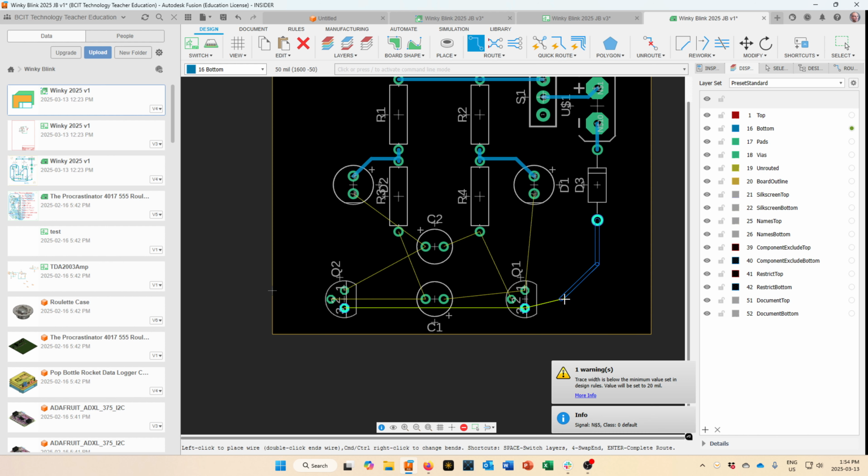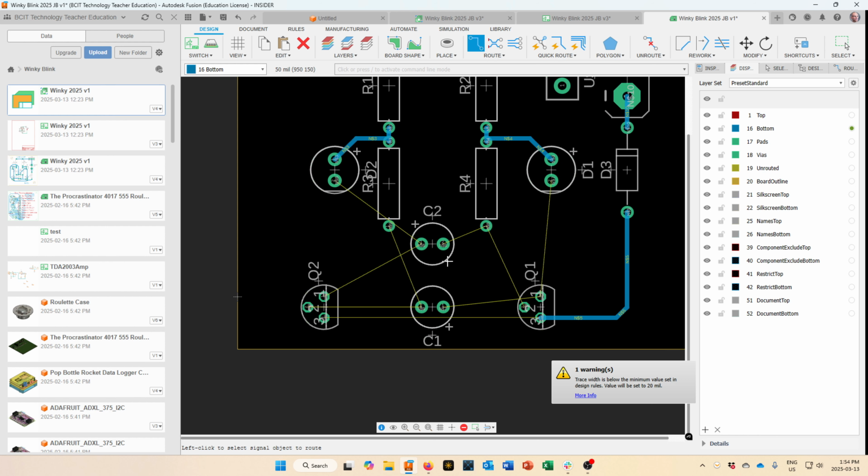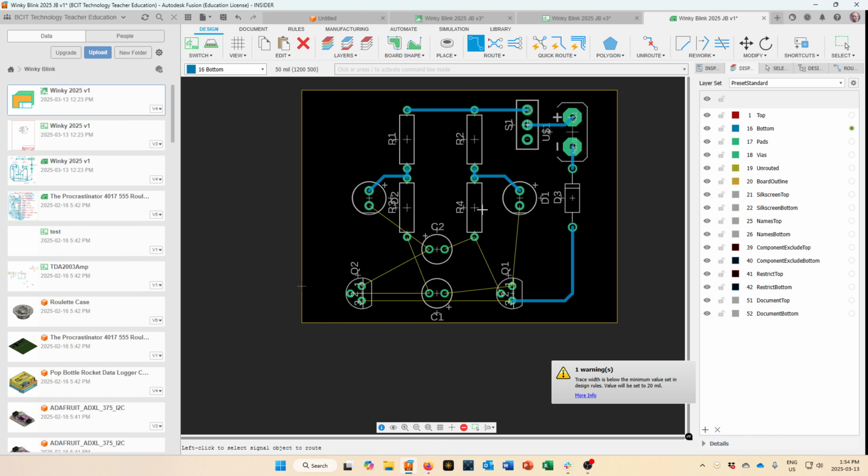It makes it easier to follow the lines and figure out what's going on the board. So for instance, down here, rather than just joining it like that, I might come down to here and then join it like that. Doing this also keeps that copper away from any other traces so that if there's a problem that you have to fix later on, you'll stand a chance of doing it. Okay, now as we've got those coming together, I'm going to pause here for a moment. I'm going to see how you do at joining the rest of them together.